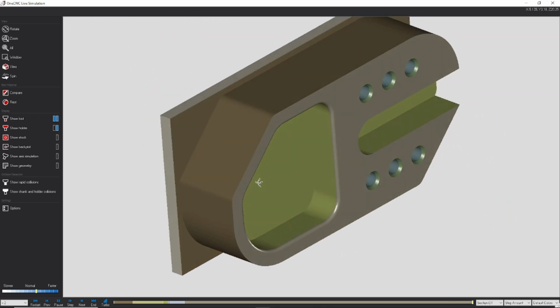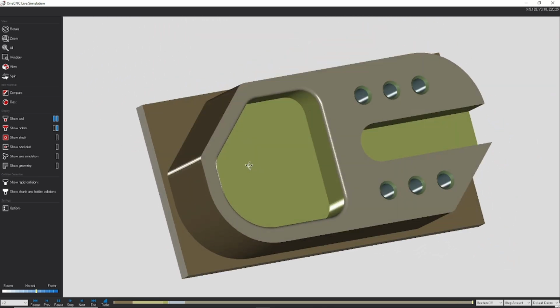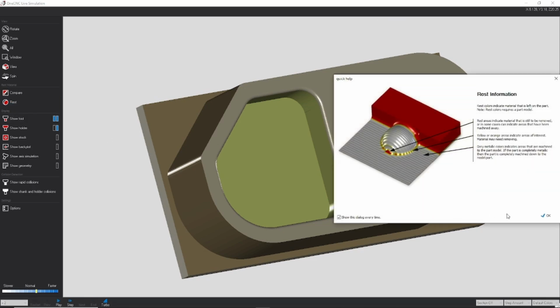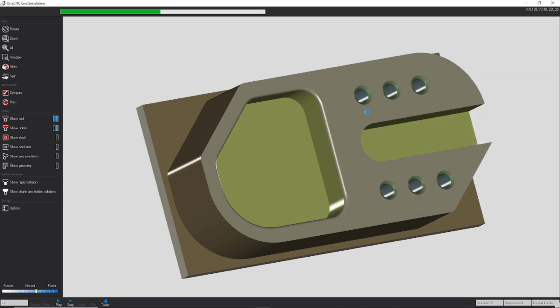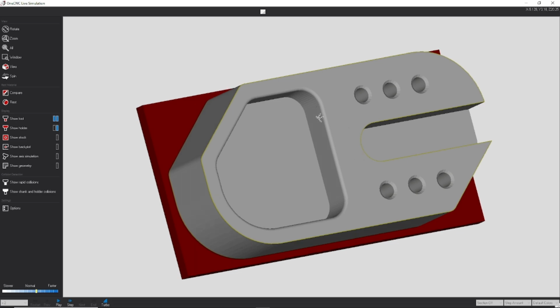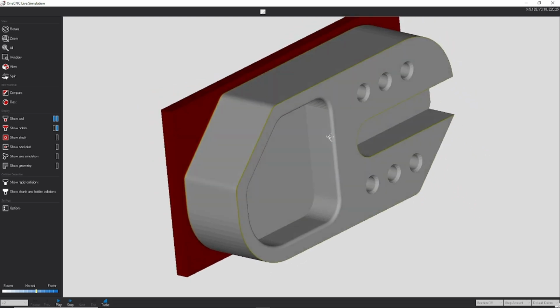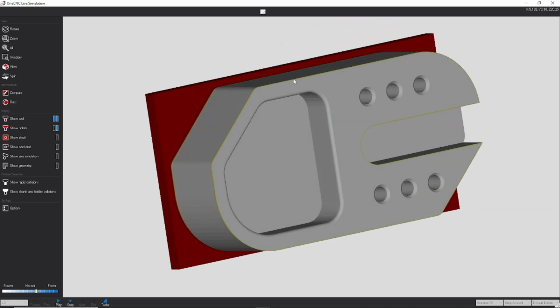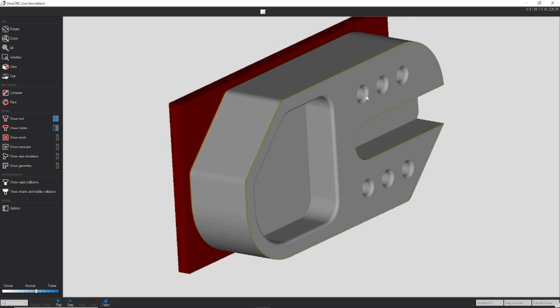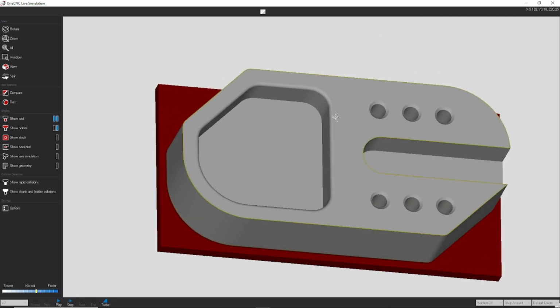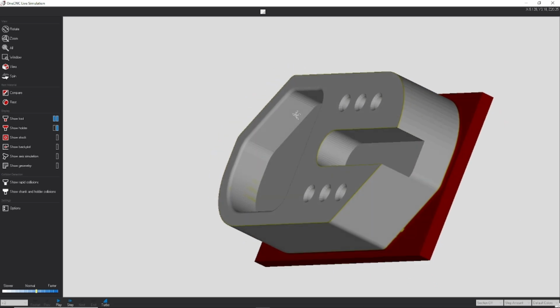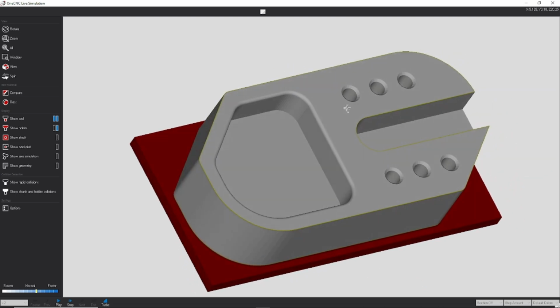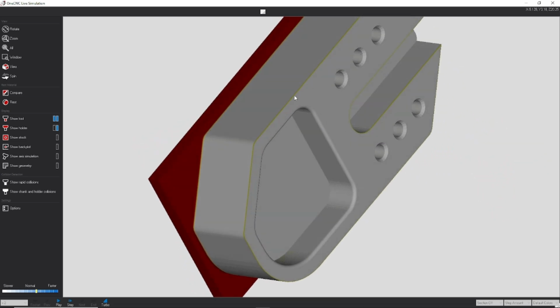There you go. Once we've got that, as a little check, we'll just rest machine it, click OK, and this is comparing what we've machined to our model. You know this little bit of yellow around here, that's obviously where it's not going to simulate the break edge, because I've cheated it by saying it's a 2mm tool when it's actually a 3, so that would make up the difference and it would cut.